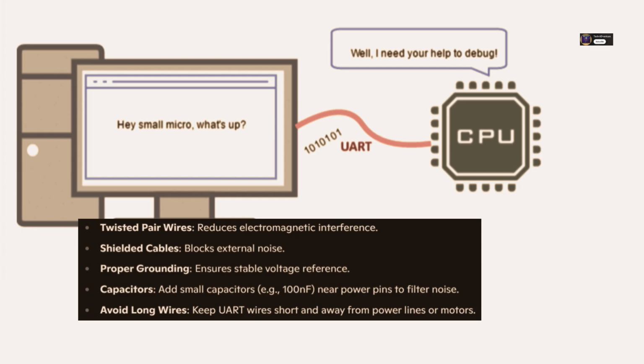5. Open your serial terminal software on the PC. Select the correct COM port. Configure the baud rate, data bits, usually 8, parity, usually none, and stop bits, usually 1, to exactly match the settings programmed into your microcontroller firmware.